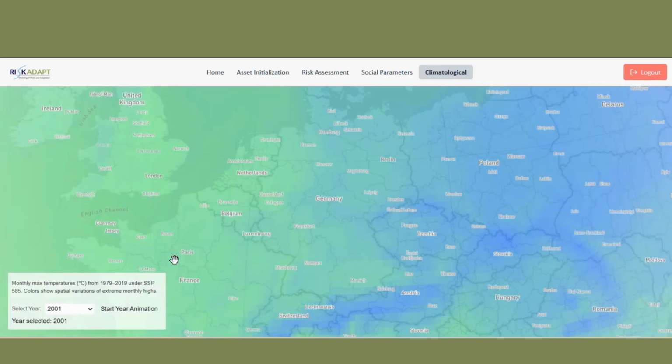Okay. This is important because there may be a difference. And then I'm not sure this would be helpful to the structural engineers if you have to say that there is no damage, let's say moderate damage is when the safety factor is between 1.3 and 1.5, and critical should be between 1.1 and 1.3.